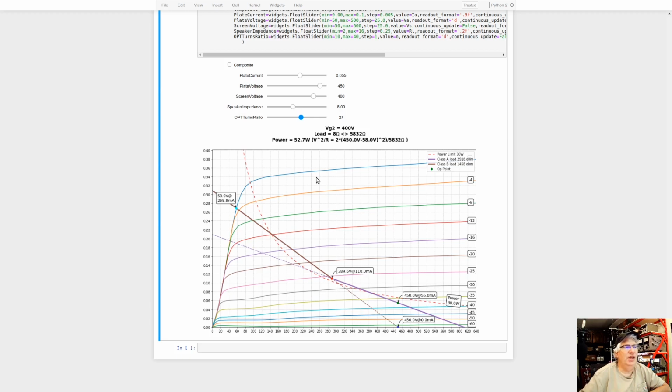If we're below the knee, what happens is over here, as the voltage swing gets near this point, because the lines are smashed closer and closer together, you don't get out as much current. So the resulting waveform is somewhat rounded off on the peaks. It's not squared off. It's rounded off, and this is a desirable distortion characteristic that you get out of tubes. So below the knee is good for guitar amplifiers. Above the knee is good for hi-fi.